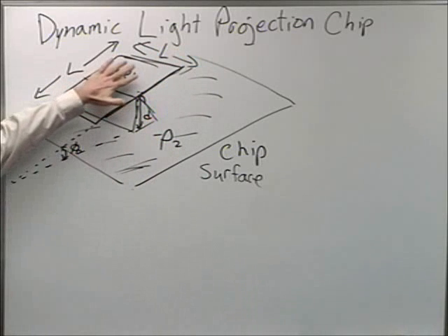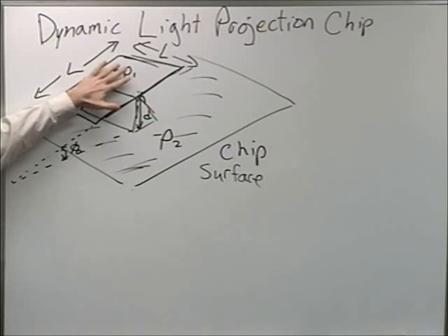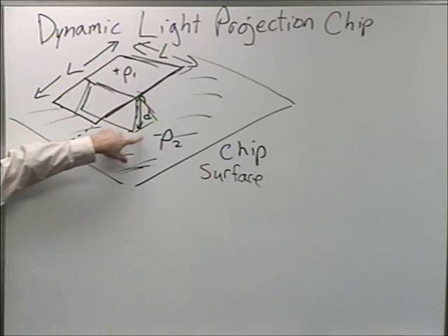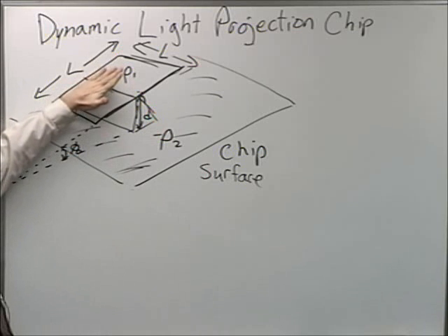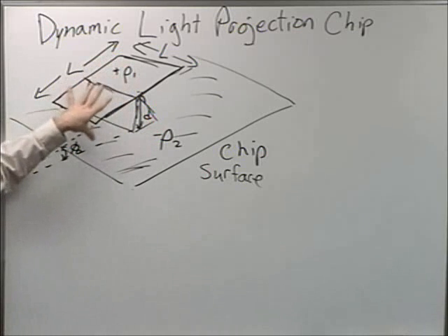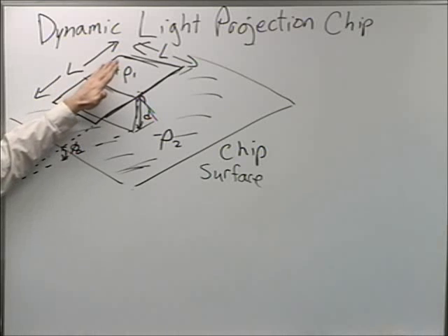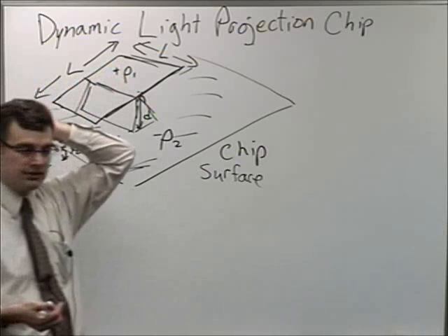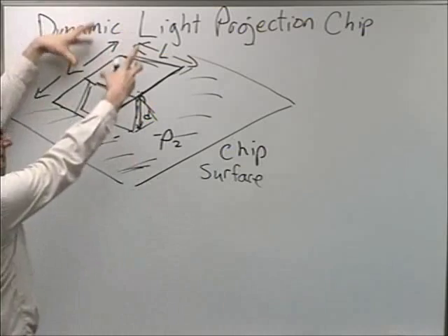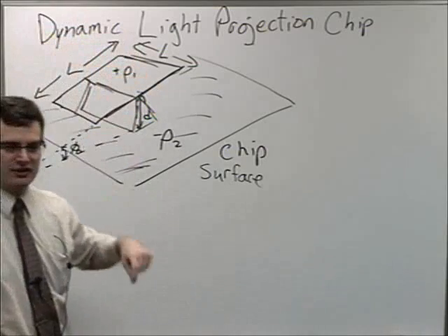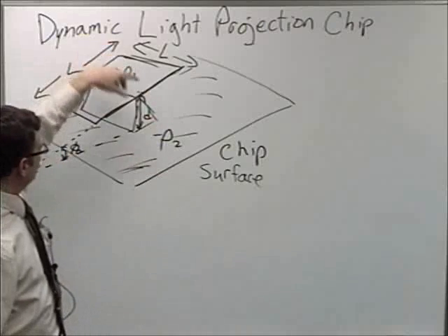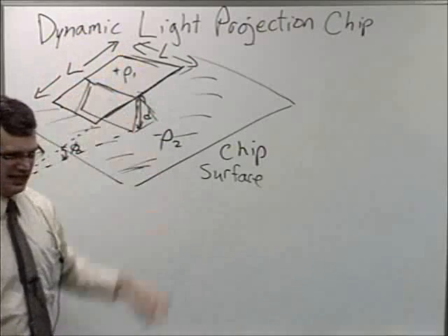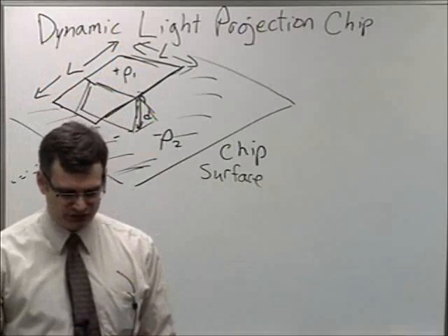You get positive charges on the table, and positive charges are attracted to the negative charges on the ground plane there, and that will apply a force, a relatively uniform force, that tilts the table a little bit and causes the mirror to deflect. Now the mirror actually rides on top of this assembly. It's not a conductor. It's a little dielectric and silvered piece. So you put that on top. We're just going to look at the charge table underneath of it.